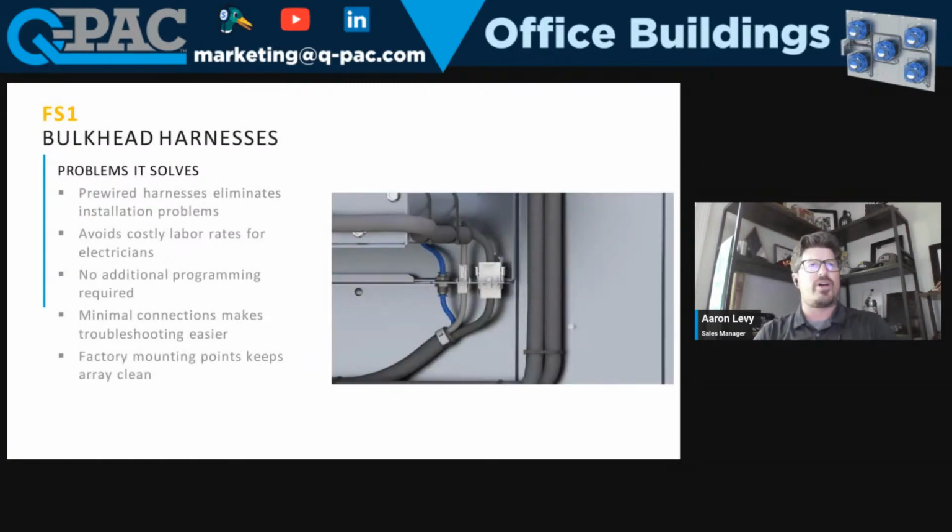And when we talked about the wiring harnesses, every fan will come with the same connection points. And then you've got wiring that comes back that we provide. That'll be labeled fans 1, 2, however many fans there are, and they'll go to their dedicated wire routing. We take all that into account from the quick connect box to the fans themselves. They're just Molex plugs. They are not weather sealed. Typically, if you're having any kind of humidity issues or outdoor air or moisture problems, silicone and dielectric grease could be a really good saver to make sure you don't run across any shorts.